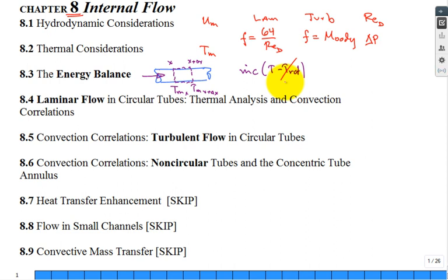All right. Likewise, you have the same equation for the mean temperature at x plus delta x, or at the outlet. So you're not taking into consideration like environmental temperatures? It's not like convection? And then coming across the side of the control volume, you'll have maybe a constant surface heat flux. And then if you multiply by the perimeter and then times delta x, that gives me the surface area, and that's what's added. So you have to do a complete energy balance.